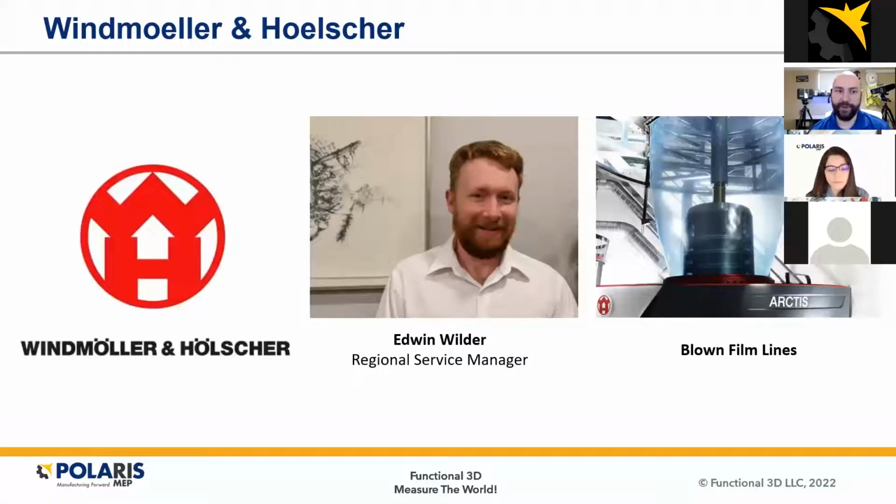I have different size tripods to be able to get up and over things, at different levels, so you're getting top down types of scans as well. I put it on top of some pallets at different points just to get it up higher, so it can avoid any of the issues where maybe someone's blocking information.